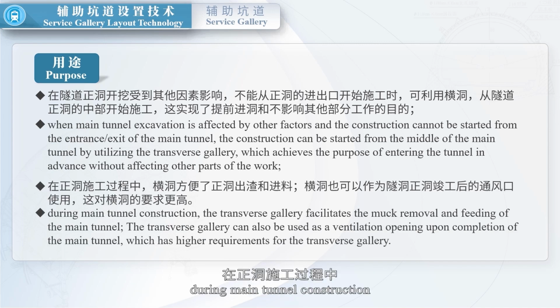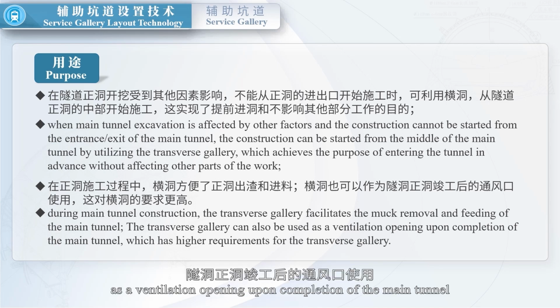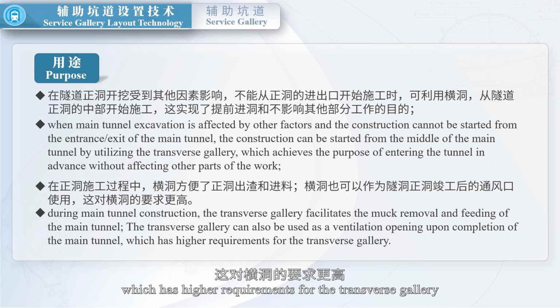Meanwhile, during main tunnel construction, the transverse gallery facilitates the muck removal and feeding of the main tunnel. The transverse gallery can also be used as a ventilation opening upon completion of the main tunnel, which has higher requirements for the transverse gallery.